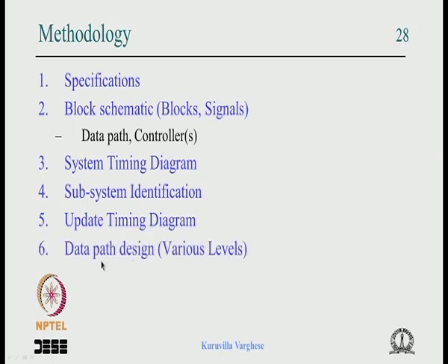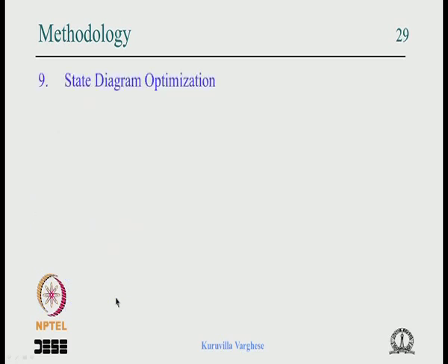Then of course we have to do the data path design. We have assumed the FIFO design is done; we have not attacked that, but ultimately you have to design the FIFO too in this case, or use a FIFO as a block from somewhere, or literally design it. So the data path has to be designed, and in a complex case you have to go through a hierarchical top down design. Then we developed the controller algorithm from the timing diagram. Then we drew the state diagram, and after that we optimized.